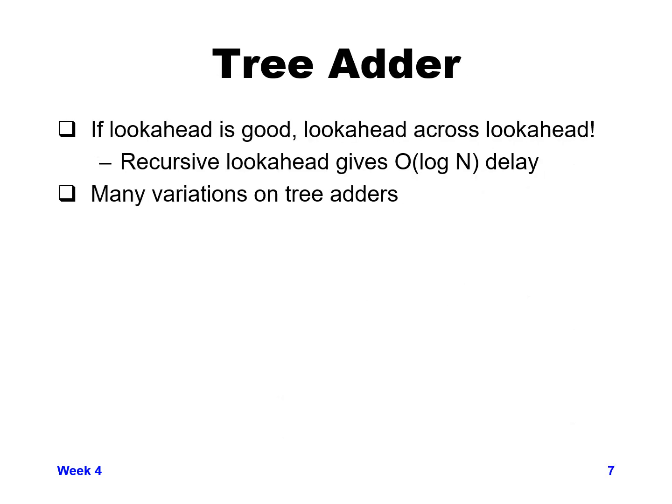So we've been doing this carry skip and carry look ahead, and as I've mentioned before, when we get to really large adders, like 64-bit or 128-bit, obviously the carry path is the dominant path through the adder. And so, we've been doing this look ahead. Look ahead is good.